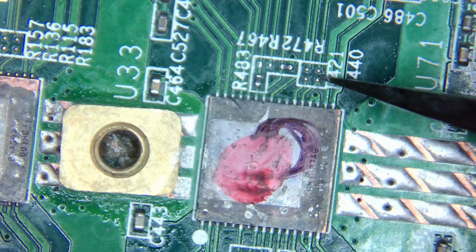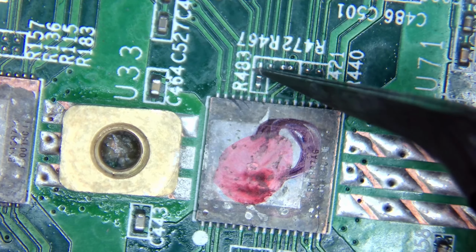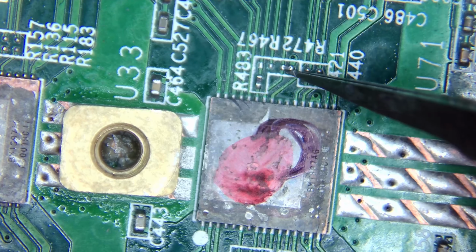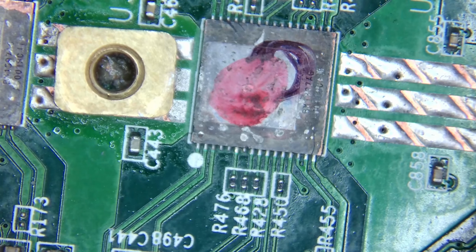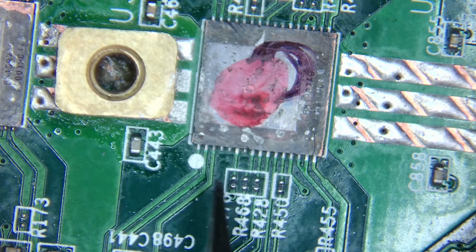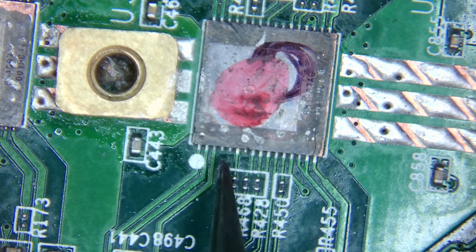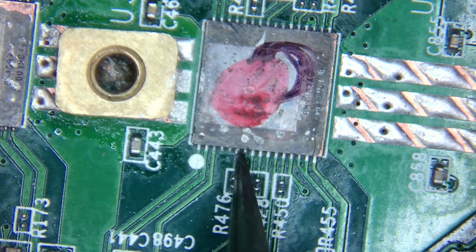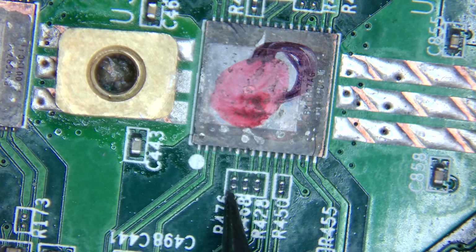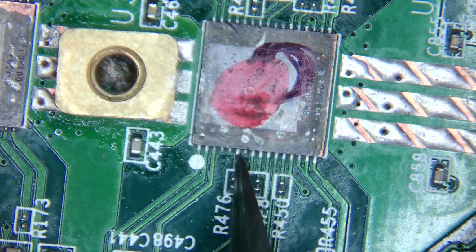And then the other one that should have a missing resistor is 467. That's right here. Okay, it's good. So this is good. This is good. Let's look at the other side. Here we go. Everything's got a resistor there. Good. So here's what I'm talking about. 4, 5, and 6. Those 3 pins are the ones that you apply resistors to, and that's how the address of the chip gets set.